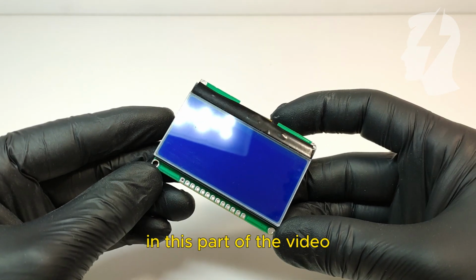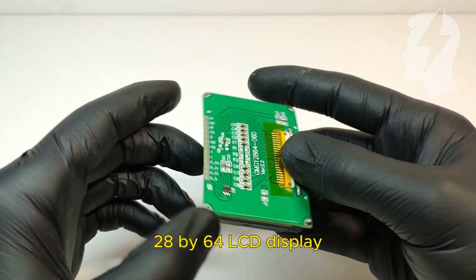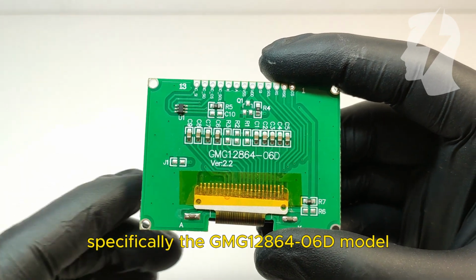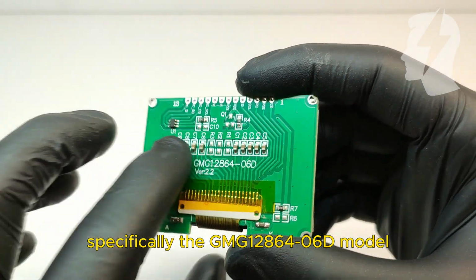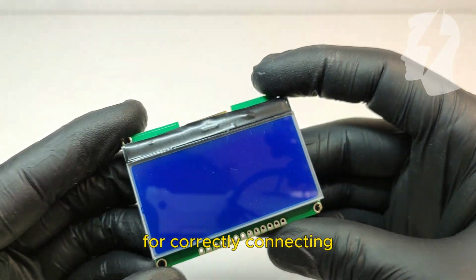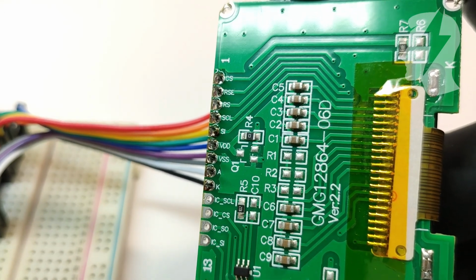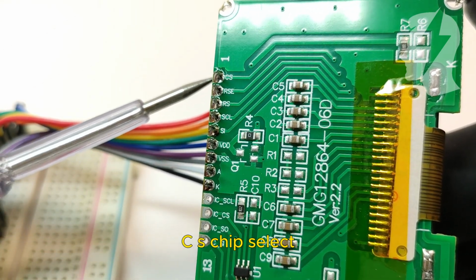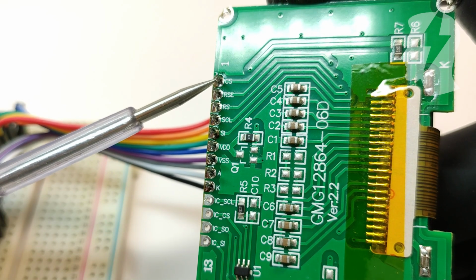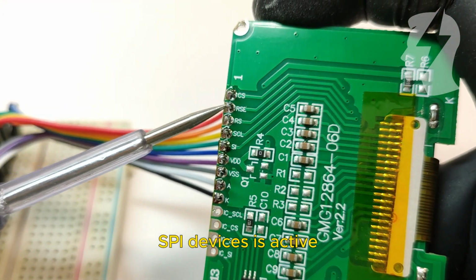In this part of the video, we'll take a closer look at the 128 by 64 LCD display, specifically the GMG12864-06D model. Understanding the functions of the individual pins is crucial for correctly connecting and using this display in your projects. Pin descriptions. CS, chip select. Used to select the display in SPI communication. This pin allows you to control which of the connected SPI devices is active.